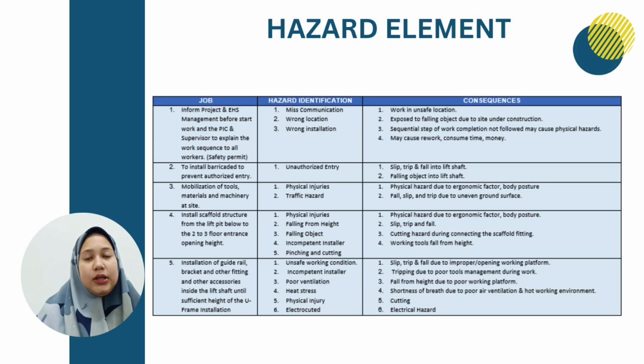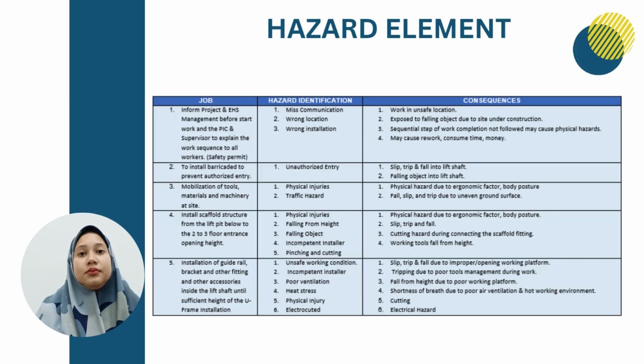Assalamualaikum warahmatullahi wabarakatuh. My name is Nur Fadila binti Fazil Isam. So I will proceed with the hazard elements that we are able to identify during the installation of the lift platform, commonly called the false car. The first step during the installation process is to inform the project and ESH management before starting the work, and also the PIC and the supervisor need to explain to all workers the sequence of the job. The ESH officer also needs to make sure there is a safety permit or work permit available before allowing the installation process.